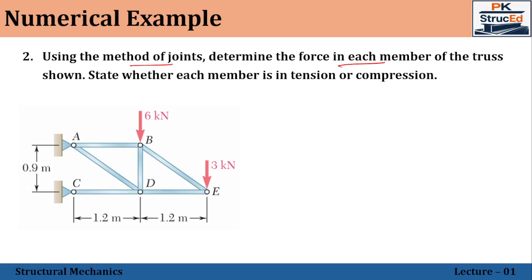Right. So in that case, that is a statically determinate condition. But coming on to this case, you can see both ends are pinned ends, which means that we'll have vertical reaction, horizontal reaction, vertical reaction, horizontal reaction. So totally 4 unknowns, which is a statically indeterminate case, which cannot be solved by using only these equilibrium equations. Right. So in that case, you have to solve with a different approach.